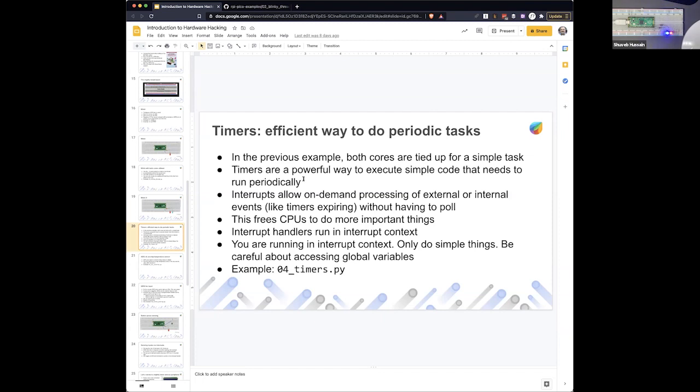But you can use hardware. The Raspberry Pi Pico has a hardware timer, right? Whenever a timer expires, it can create an interrupt, and then it can run any routine you want. For example, think of it like a callback. It's not really a callback, calling it a callback is ridiculous, but it's like a callback. Say the timer expiration is 1 second. The timer will expire every 1 second, and it will call an interrupt function. It's like a callback, to trivialize and oversimplify things.